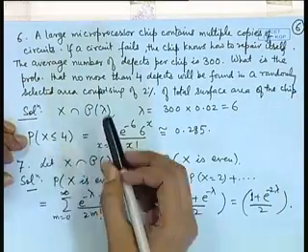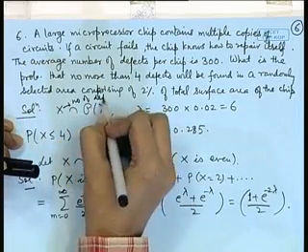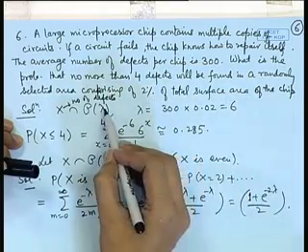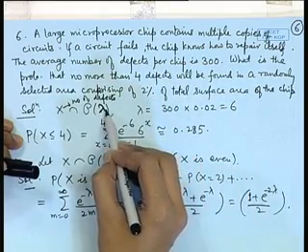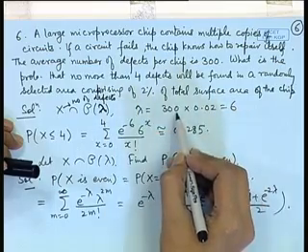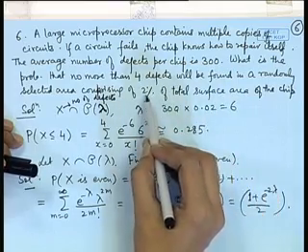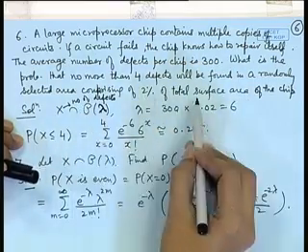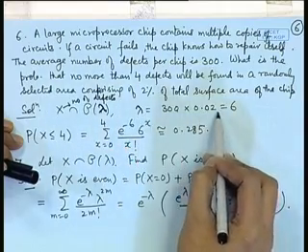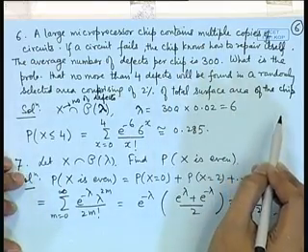So, here if I consider x as the number of defects in the 2% of the surface area, then I assume it to be Poisson distribution with parameter lambda. Lambda here will be, because 300 is for the full area, 300 into 0.02. That means in 2% of the surface area, what is the number of defectives? For that the rate will be 300 into 0.02, that is 6. That is the rate of detecting the defects.